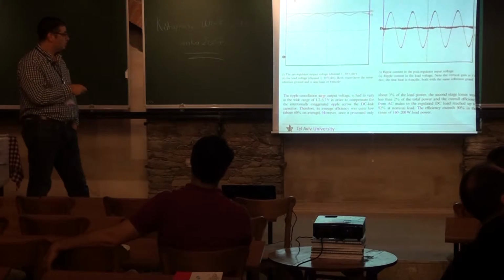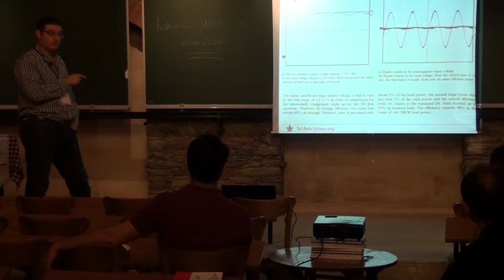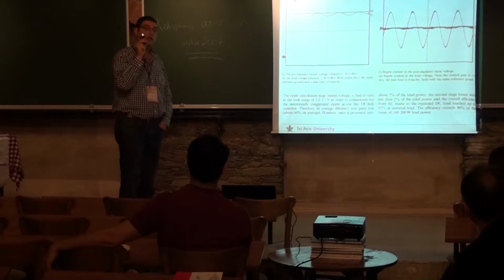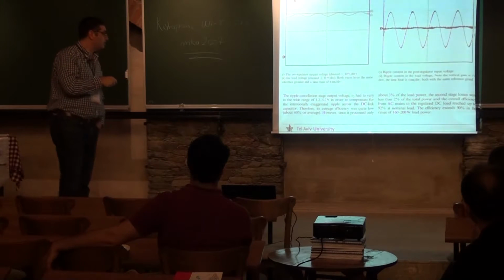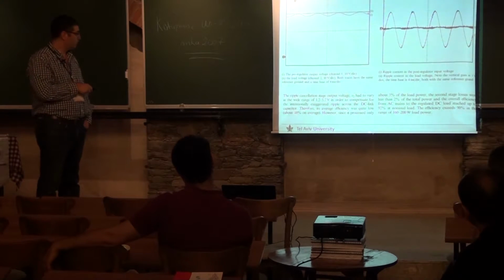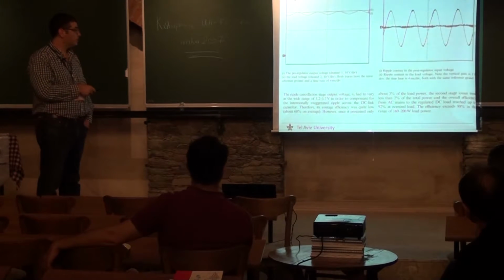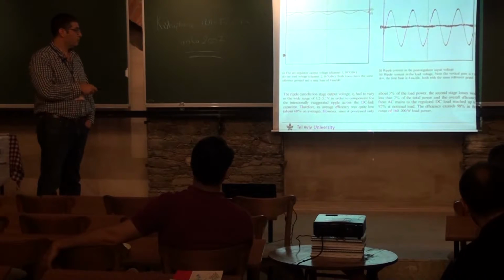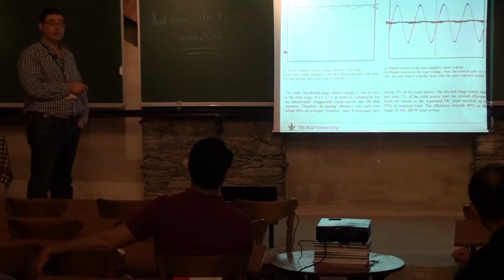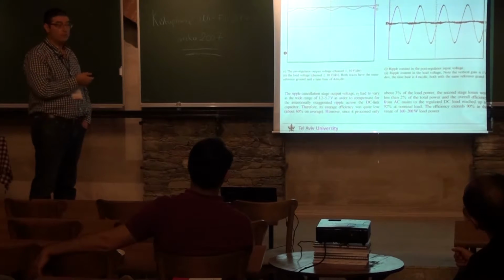The variation of the voltage is in this full range of 1.2 up to 5.7. Obviously, the efficiency is very low, about 60%. The efficiency of the ripple canceller by itself. But at the system level, we reached some 92% efficiency, regardless of this 60%. Again, because of the low power that is being processed, and in the range of 160 to 200 watt load. So that's a second example of partial power processing.